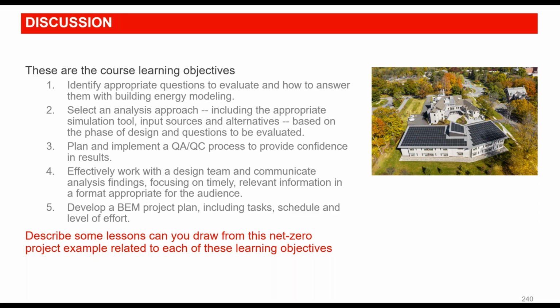It is, but I think if you're in a situation where you're worried about moisture penetration, WUFI can be a tool to assuage that. I know some of the building energy model interfaces have tools to show you where, on design conditions, you can expect to see condensation, and you can adjust insulation levels to make sure that's not in the middle of the wall. So that's a key thing to understand there.